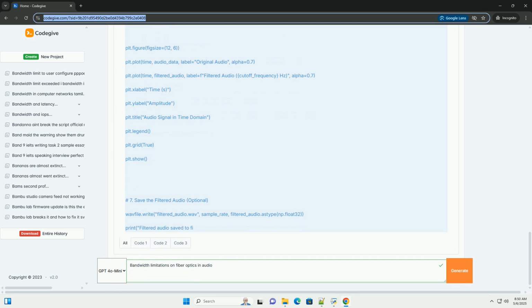Optimize transmission distance: keep cable runs as short as possible to minimize attenuation and dispersion. Use appropriate protocols and encoding: choose digital audio protocols and encoding schemes that are efficient and suitable for the application. Avoid unnecessary overhead. Consider lossless compression if bandwidth is a critical constraint.